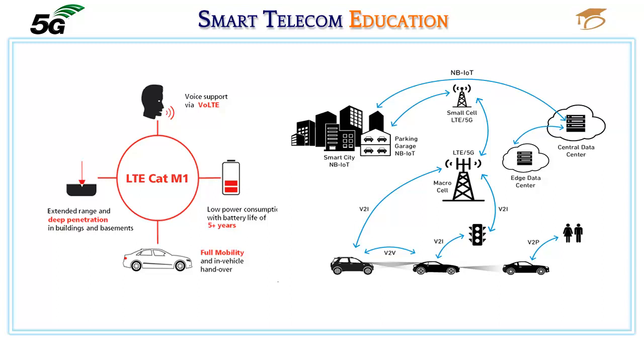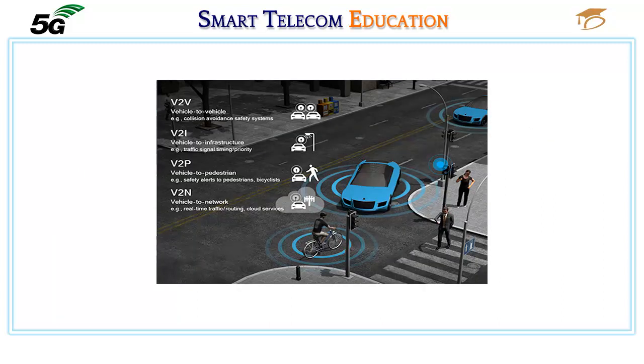However, in order to enable complex vehicle maneuvering, determining and recommending individual actions, for example acceleration, deceleration, lane changes, or route modifications, the vehicles must be able to share and receive information about their driving intentions in almost real time. This low latency demand certainly requires the development of an overall 5G system architecture to provide optimized end-to-end vehicle-to-everything (V2X) connectivity.